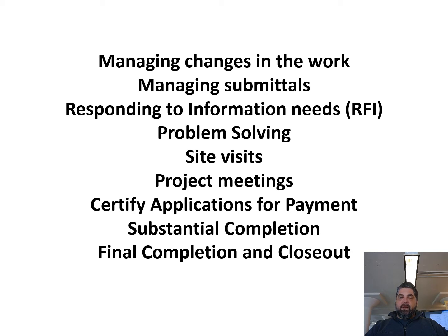There's a lot of things that lead up to that, and making sure that you have that, and that your punch list typically coincides with the substantial completion. To confirm, or to put the substantial completion date in ink, so to speak, you will prepare a document called a certificate of substantial completion that will list any outstanding items, also known as your punch list, and any closeout items that are remaining by the general contractor.